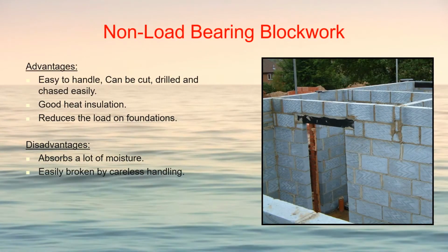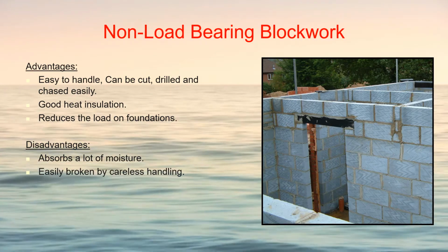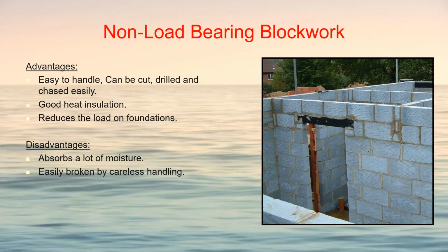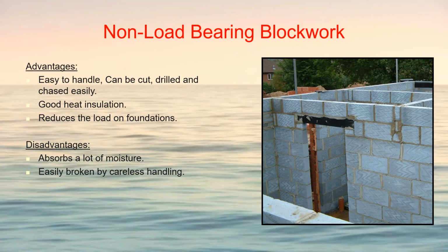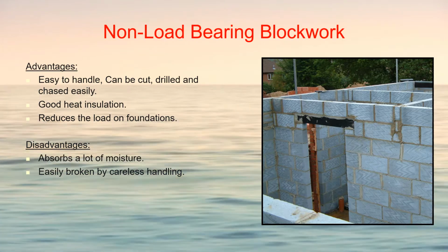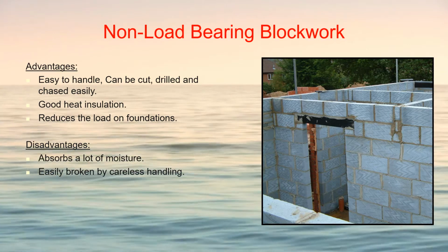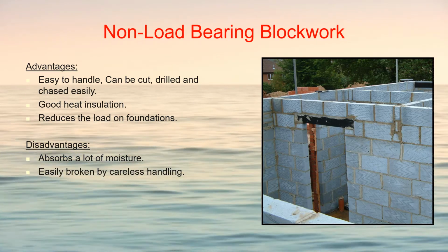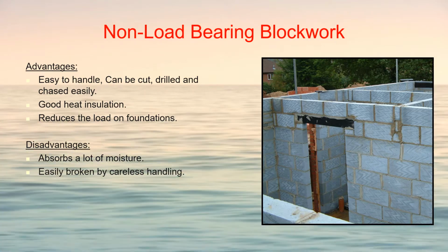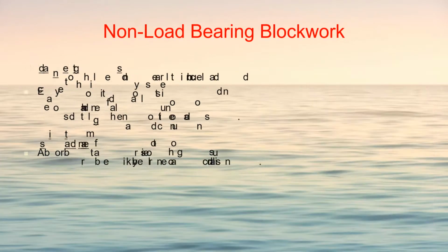The advantages of non-load bearing blockworks are: number 1, easy to handle, can be cut, drilled, and chased easily. Number 2, good heat insulation due to voids that trap air. Number 3, reduce the load on foundations due to lightweight. However, there are disadvantages as well, such as: number 1, it absorbs a lot of moisture due to porosity. And number 2, it is easily broken by careless handling because the block is less solid.